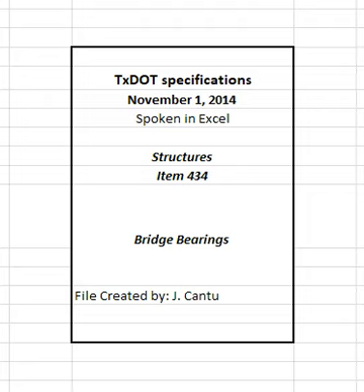3.2.4 Field Methods. Provide concrete surfaces for bearing areas under sliding elastomeric bearings in accordance with Section 420.4.9, Treatment and Finishing of Horizontal Surfaces. Refer to the plans for temperature setting corrections for all bridges and bearing alignment relative to chord for curved bridges. Perform such adjustments as directed if the plans do not address these requirements.